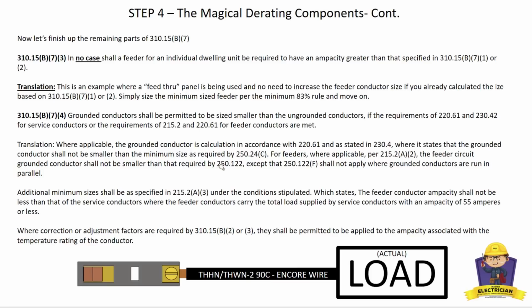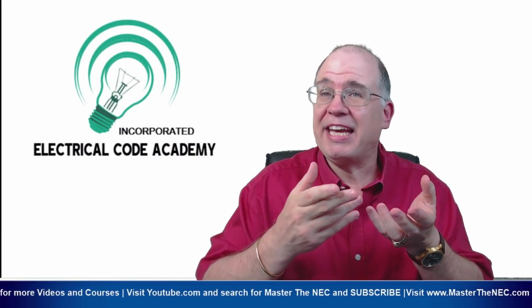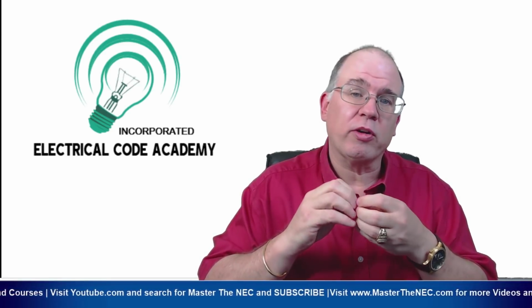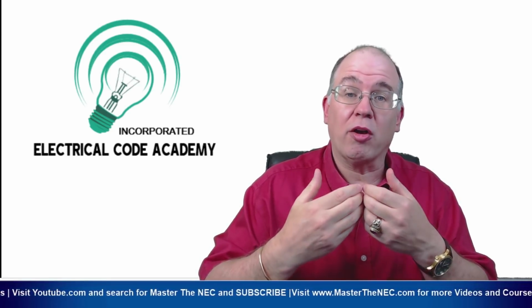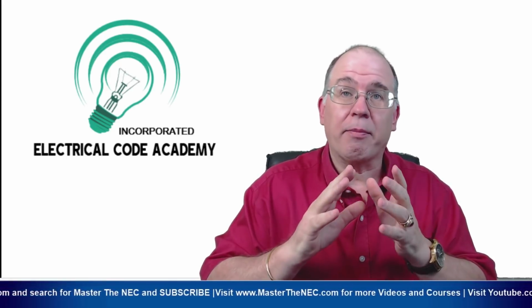Now, what this is basically saying in a nutshell is that you might have a case, and you do with SE cable all the time, where you're going to have a neutral conductor that might end up being smaller than the phase conductors. And that's okay. Not a problem.